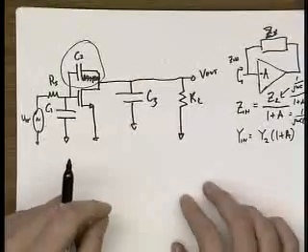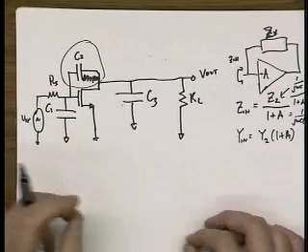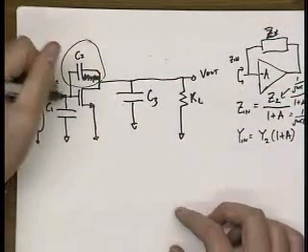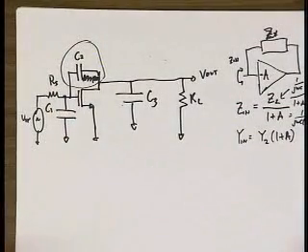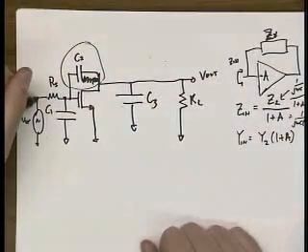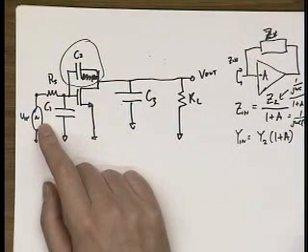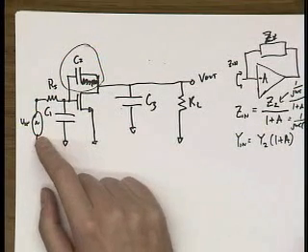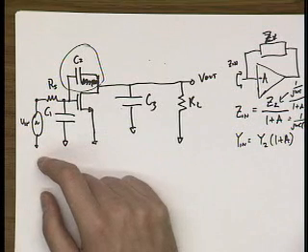But that's how that effective capacitance gets Millerized, okay? So, question one in analyzing a circuit like this is, how many poles are there? I told you there are 2 poles, and you can sort of guess that there are 2 poles because there are 2 nodes. Well, there are 3 nodes, but this node here is connected to an ideal voltage source, right? So it has 0 impedance connecting it to a small signal ground, so it won't have a pole.